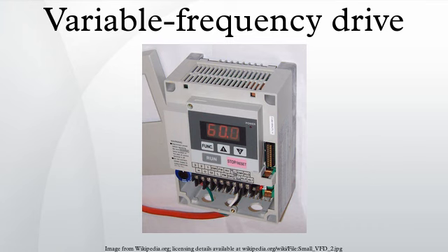Although space vector pulse width modulation is becoming increasingly popular, sinusoidal PWM is the most straightforward method used to vary a drive's motor voltage and frequency. With SPWM control, a quasi-sinusoidal, variable pulse width output is constructed from intersections of a saw-toothed carrier frequency signal with a modulating sinusoidal signal which is variable in operating frequency as well as in voltage.